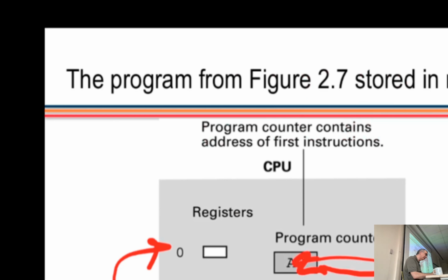And the program counter increments 2 by 2: A0, A2, A4, A6, A8. The increment step is determined by the architecture. This machine increments 2 by 2 automatically because it is a 16-bit instruction type by design.